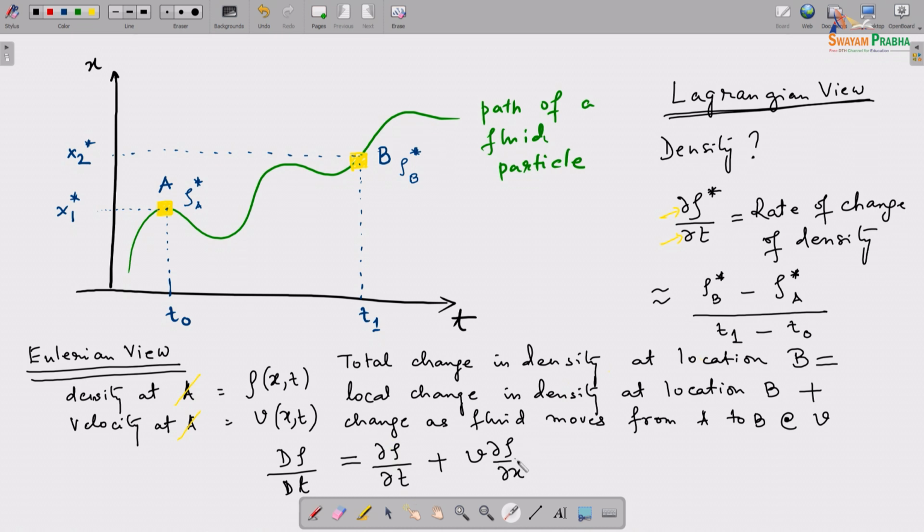So that is also actually the total change in time, in this time, but then this change is due to the change of location, right, and this first term basically represents the entire change during the instant of time, right. Of course, here delta t tends to zero, by definition it is a very small value. Okay. So that is essentially your Eulerian view and Lagrangian view.